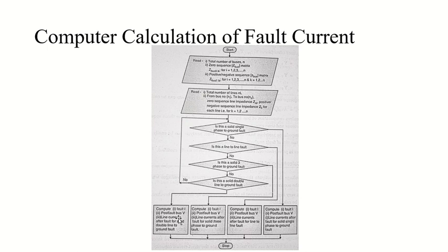The currents and voltages that activate the relay are the currents and voltages which flow or appear immediately after the fault occurrence. And we all know the fault current is normally very high, and who interrupts that? It is interrupted by my circuit breaker.